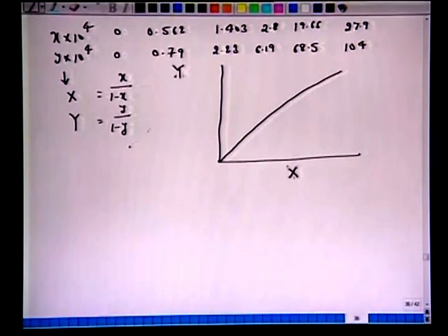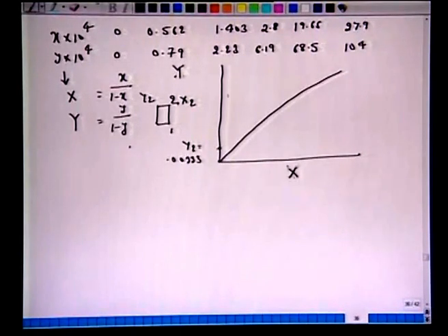So, let us mark the points here. We have been given 1 and 2, this was our column at location 1 and 2. Okay, we knew x2 pure solvent and we knew y2. So, we can immediately mark this point as 0 for the solvent, and we had this y2 given here 0.00333. y1 we know, this also given to us, y1 as 0.111. So, be careful when you plot, not necessarily you have to plot from 0 to 1. For larger resolutions you should work only between the two limits 0.00333 and 0.111.